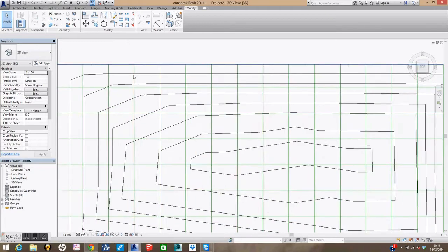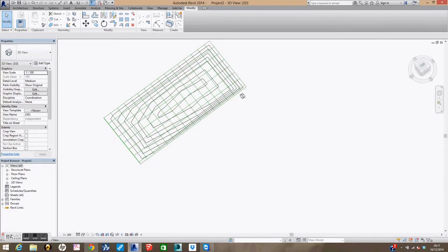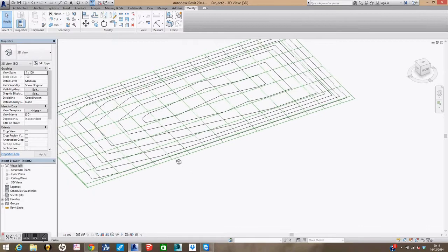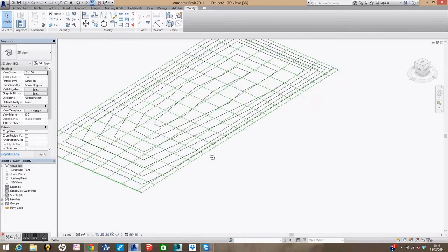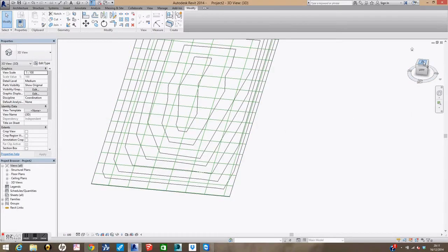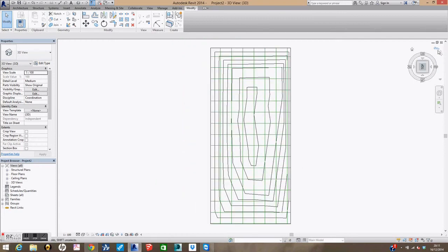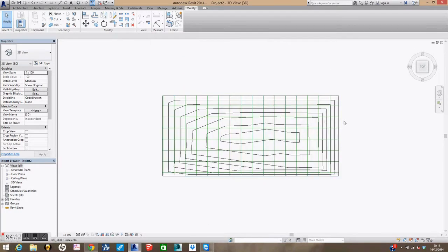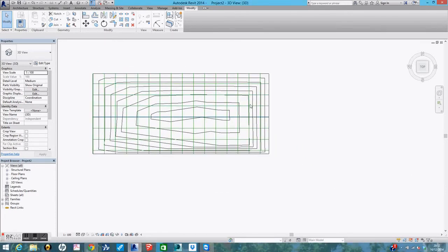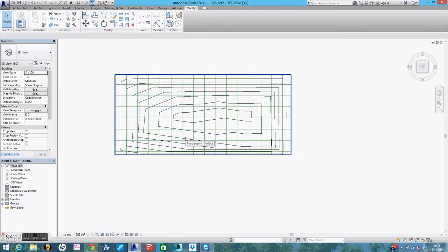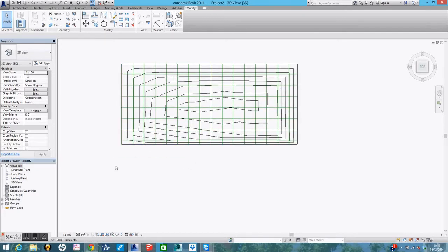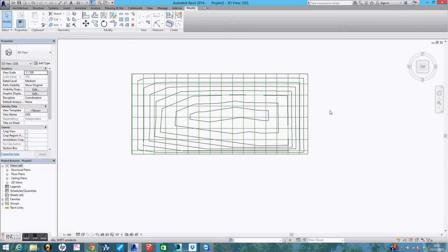So, okay, I've made a grid, and what I'm going to proceed to do now is locate a whole bunch of my little site points that I just created onto the points of that grid. So as I generate the road, I've got something to follow. I mean, you could have an AutoCAD plan or something to go underneath all of this, whatever. But I'm just going to arbitrarily create a road surface here and sketch it on later.